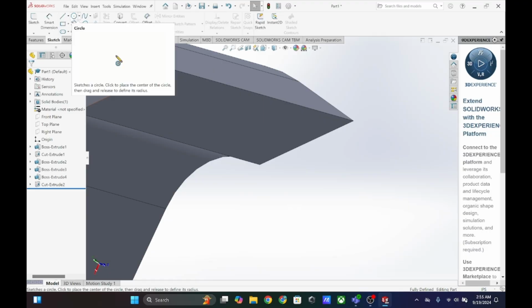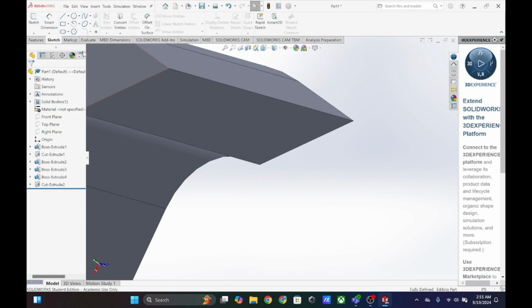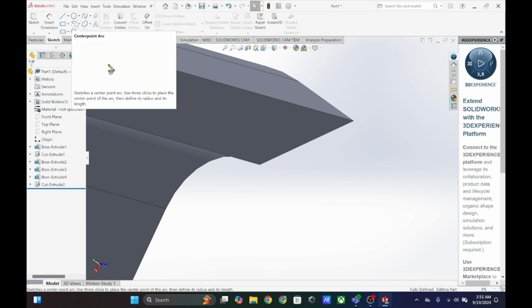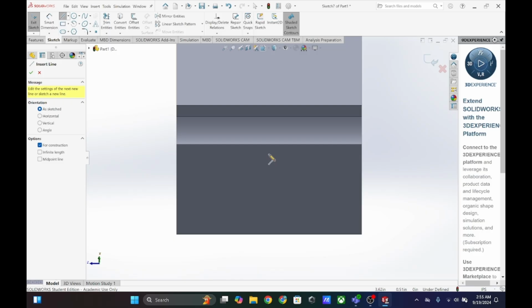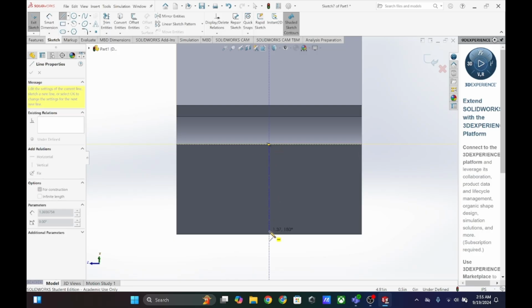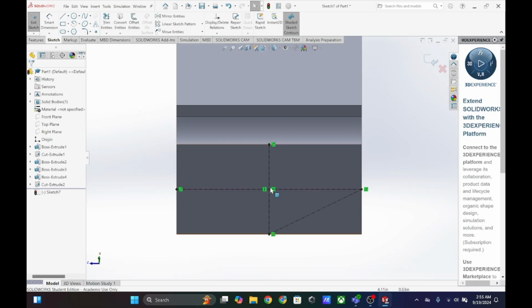All right, now at this curved edge, the last step of this part, we are going to add in a kind of knob holder for where we will put the magnifying lens part. So let's do some center lines to get the center point of this surface. Kind of move your mouse around until this orange line pops up, and we're going to go down. And then I like going to find the center line. You can go across and then go across once more, ensuring that it is all perpendicular. Now this point right here is the center.